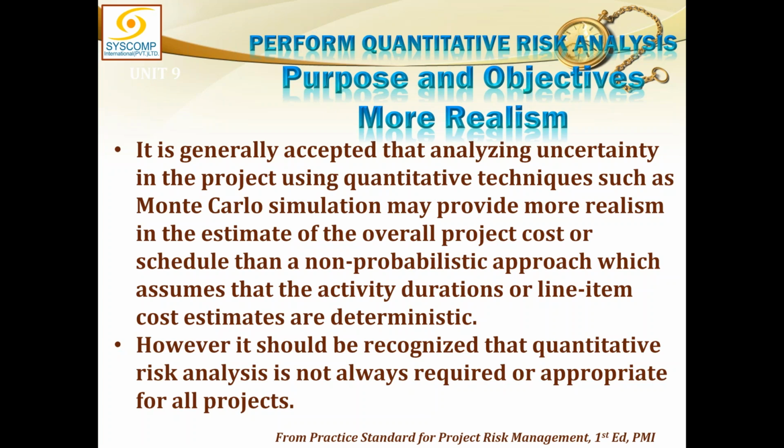So the immediate use of 3-point estimate is that we have calculated an estimated duration for that activity by the formula, optimistic plus 4 times the most likely plus pessimistic, divided by 6. And if you have not done that, you also can calculate the standard deviation out of it. Can someone tell me how you can calculate the standard deviation out of it?